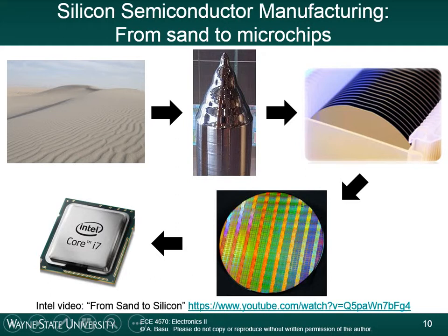Those regions are defined through processes called photolithography and diffusion. They use things called wet etching, dry etching, and things like that to define them. We're going to be talking in detail about those later, so we're not going to go into that now. When the wafer is completed, you usually have hundreds or thousands of microprocessors on there, and then it is sliced up, vertically and horizontally, to form these individual chips. Those individual chips are bonded to a printed circuit board, which is ultimately placed into your computer. It's also placed in a package to help keep it cool.